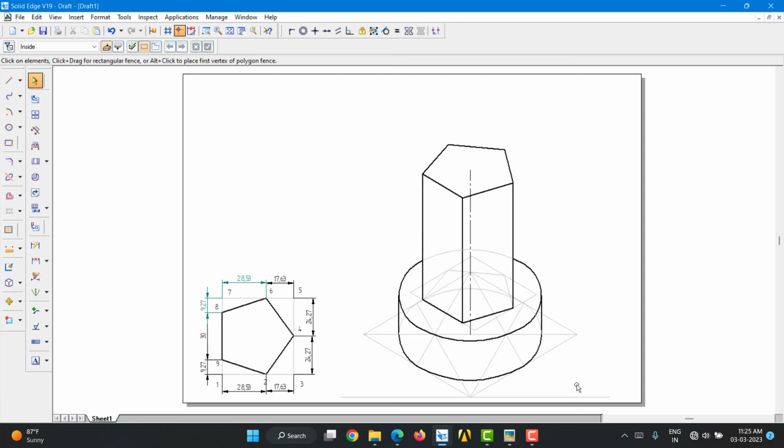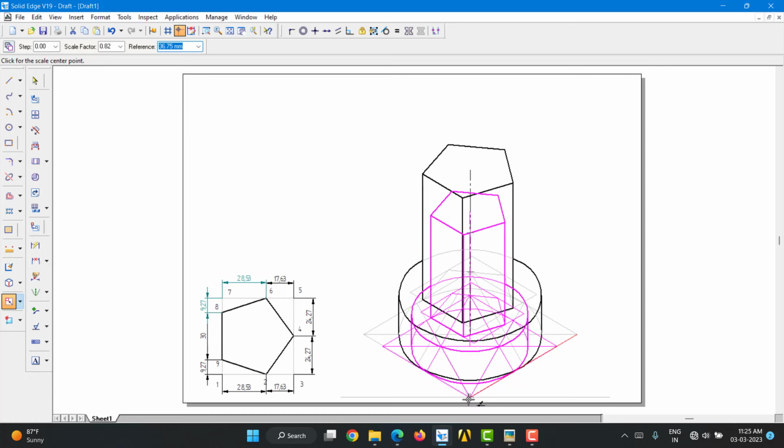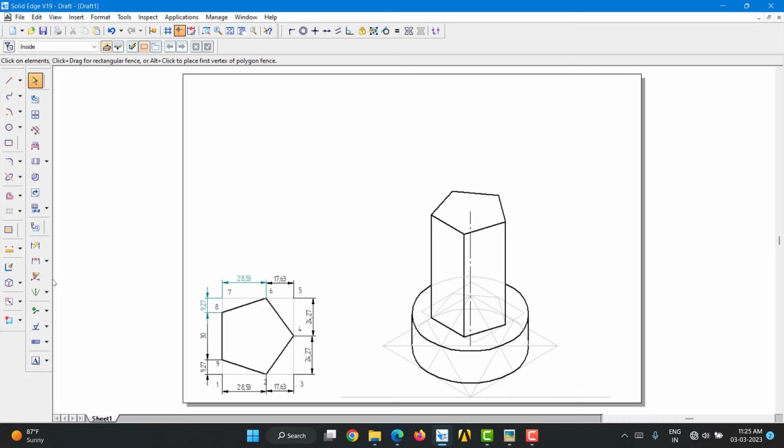Now it is to be reduced to isometric scale. So far it was to the actual scale. Go to scale factor. In scale factor, sorry, 0.8164. So it will round off, it will take 0.82. So place it exactly at that point. You can show the dimensions, like you can show 30° on either side. That can be shown like this. From here to here, you can show 30°.